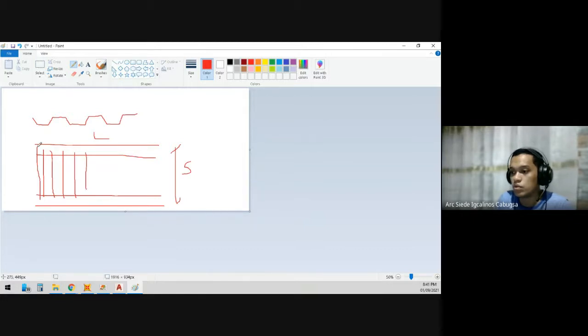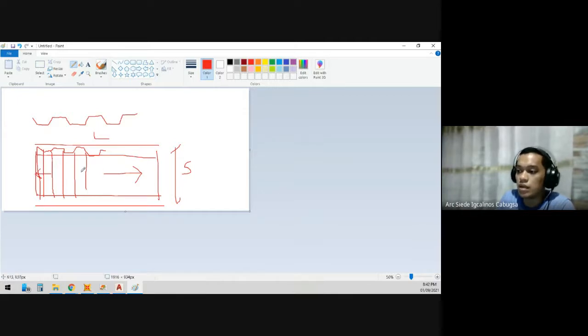So these are your grooves. The way steel decking distributes the load is one way because of its grooves. It's hard for steel deck to distribute the load to these two beams. It will always distribute the load perpendicular to its grooves. So it only distributes the loading in this direction. That's why your steel deck is always a one way system.